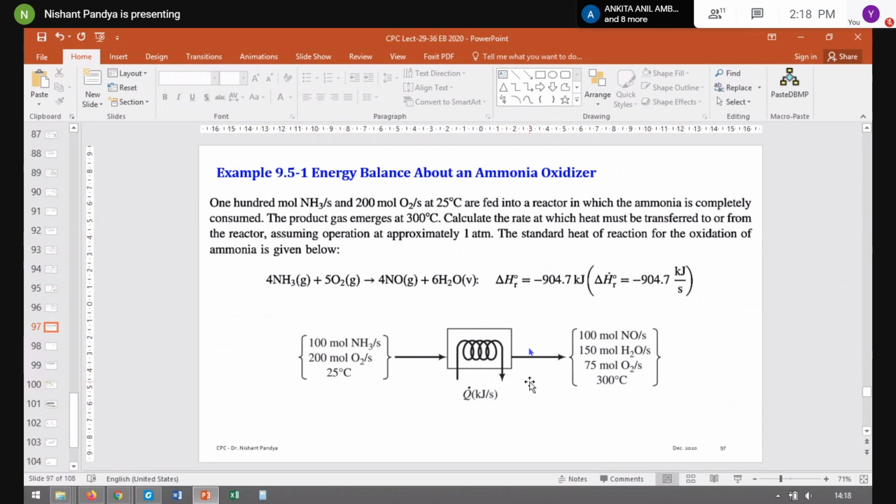Right. So see, the problem of reactions, one part is this way where you have enthalpy of reaction. You can do it this way. And if you don't want to go by this method or the data are not available, you can take N2, O2, H2 as a reference state, elements as a reference state. And in that case, you need enthalpy of formation of each component plus enthalpy change due to temperature. Those two parts you have to add.